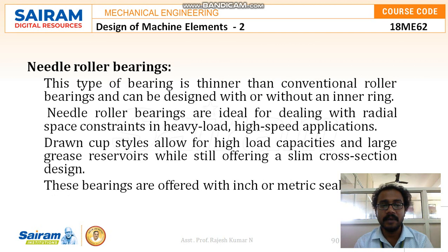Moving to the next type, needle roller bearings. This type of bearing is thinner than conventional roller bearings and can be designed with or without an inner ring. Needle roller bearings are ideal for dealing with radial space constraints in heavy load, high speed applications. Drawn cup styles allow for high load capacities and large grease reservoirs while still offering a slim cross-section design. These bearings are offered with inch or metric sizes and seals.